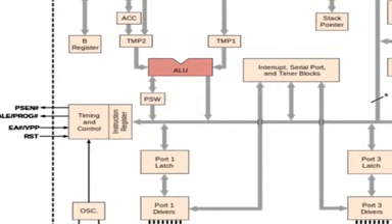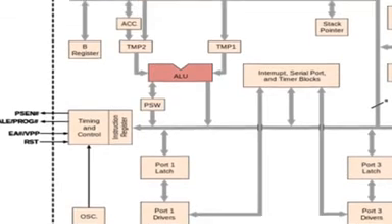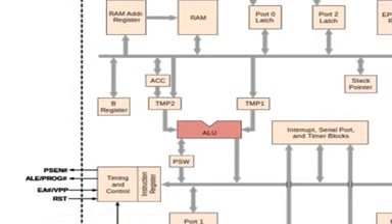Then you have the accumulator. The accumulator is also an 8-bit register. It is used for all arithmetic and logical operations. So whenever you write a program, A must be used as the destination for all addition and subtraction operations. If you are writing an addition operation, ADD is the instruction.